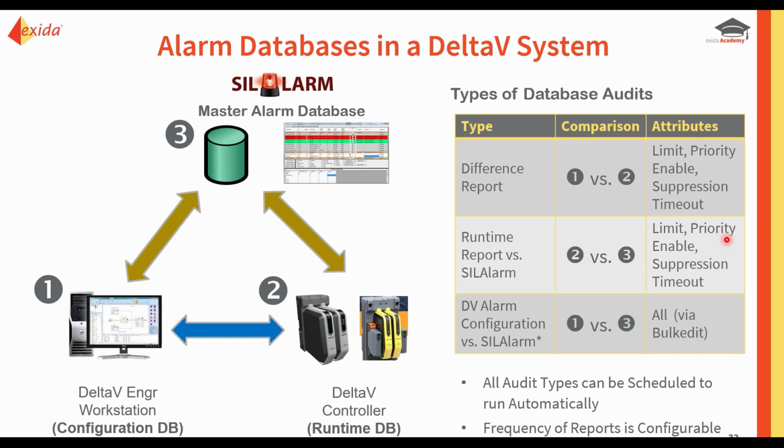If you want to do a complete audit of all alarms and all alarm attributes, then we use the approach of extracting a snapshot of the alarm configuration via bulk edit and comparing that to the master alarm database. So that's our third option here. So we can actually combine these and create something that's the best of both worlds.